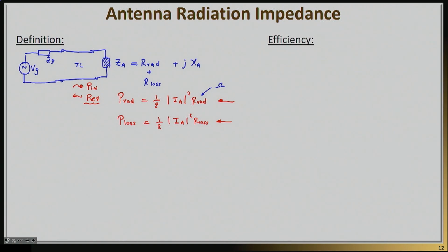So normally people will go ahead and insert a matching network right here to essentially minimize the power reflected by this antenna. So essentially, out of my incident power or my input power to the antenna, I have two potential losses, the reflected power and the lost ohmic power, and then I have one useful power that I'm basically trying to maximize. So based on that, I can also define the efficiency of an antenna, which we defined before.